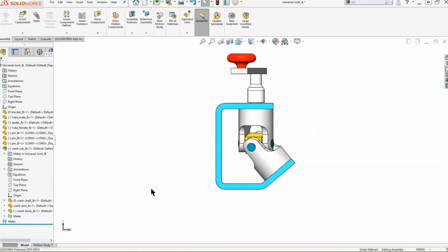So a couple of things that you can do there using the coordinate system in the lower left-hand corner: Shift and the arrow keys, 90-degree rotations; Alt and the left and right arrow keys, rotating, maintaining that kind of vector out of the screen.